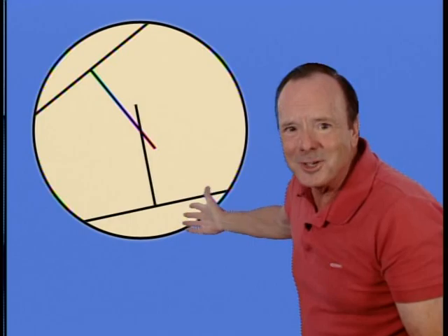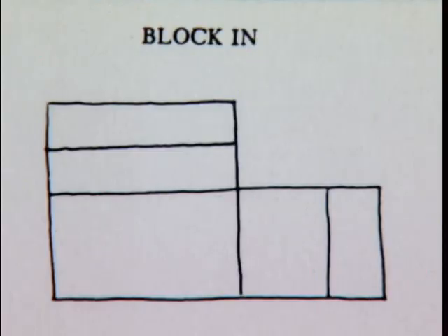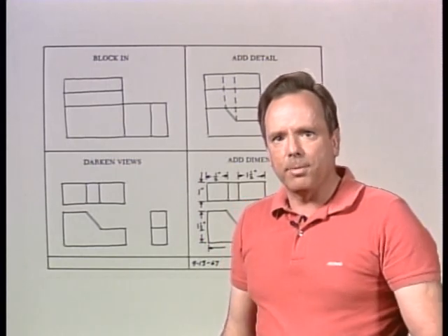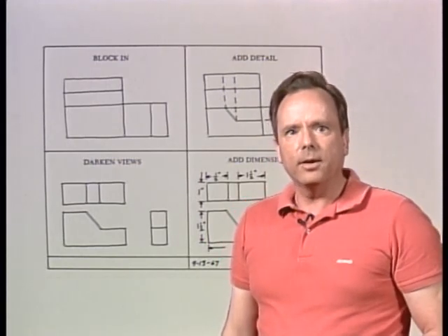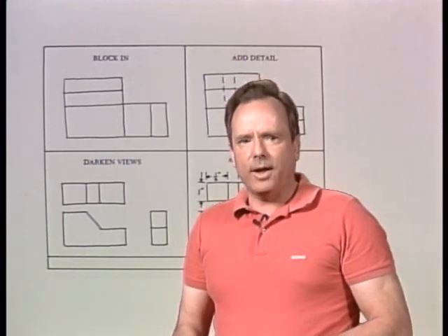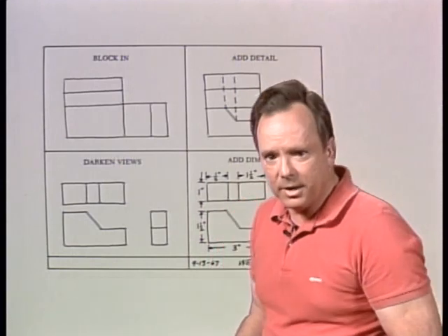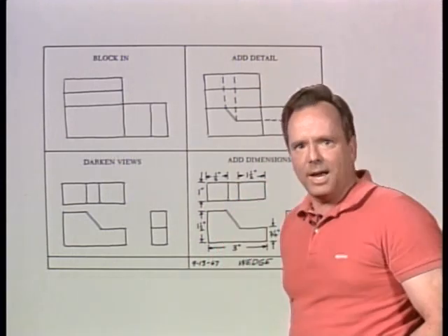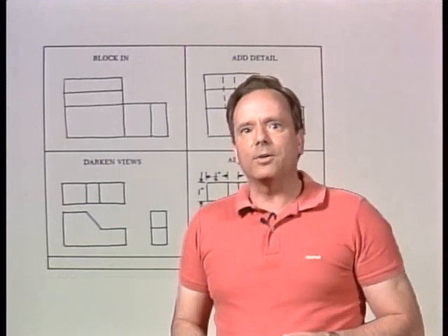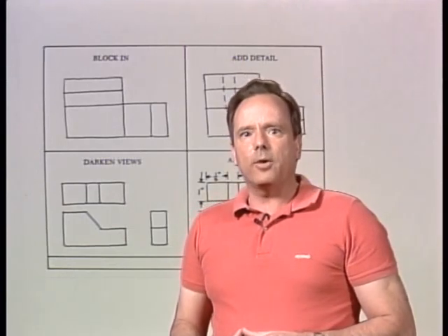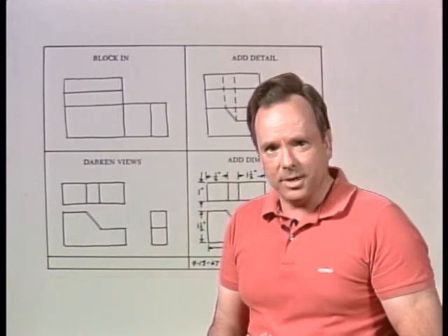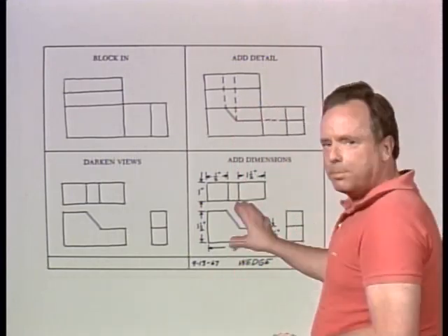See? It's easy. But sketches are frequently drawn for use in manufacturing a replacement part, and a sketch, if it's used in making a part, has to show all the information for making it. Occasionally a mechanic will use the sketch to repair an aircraft, a new design, or a modification. So as a mechanic you might need to make a sketch sometimes, and they want you to know about how to do that. By the way, there is no requirement in Federal Aviation Regulation Part 91 that repairs to an aircraft skin have a detailed dimensional sketch included in the permanent records. That is not required.